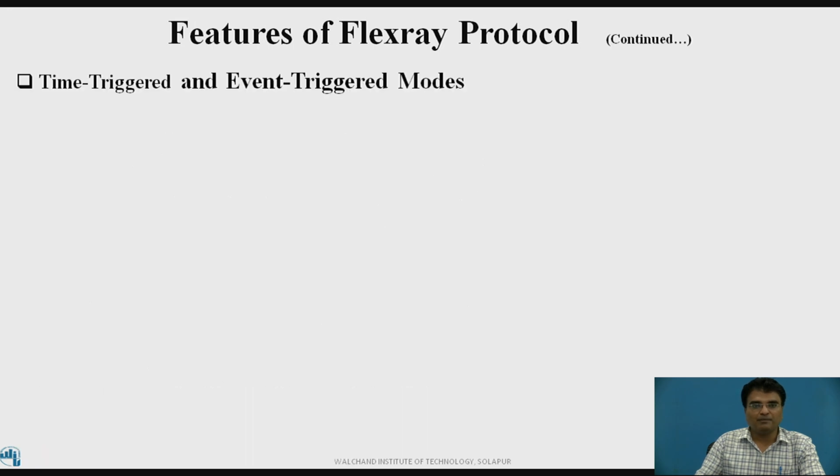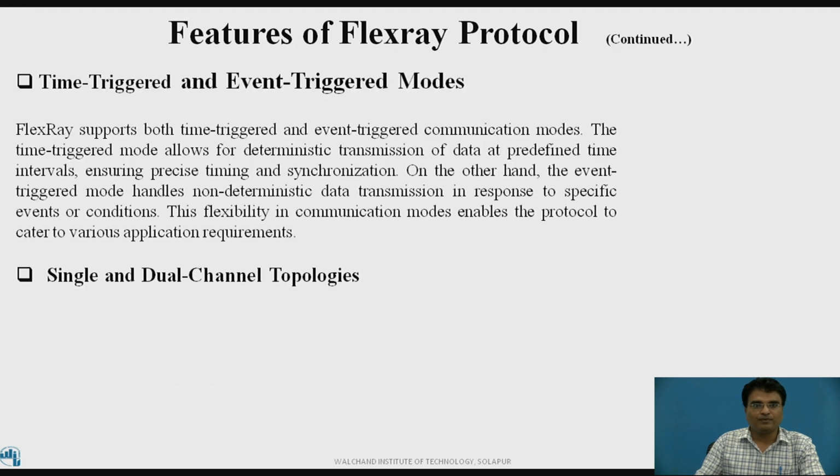Next feature, time-triggered and event-triggered modes. FlexRay supports both time-triggered and event-triggered communication modes. The time-triggered mode allows for deterministic transmission of data at predefined time intervals, ensuring precise timing and synchronization. On the other hand, the event-triggered mode handles non-deterministic data transmission in response to specific events or conditions. This flexibility in communication modes enables the protocol to cater to various application requirements.